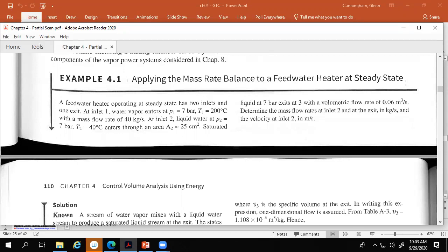So what they have is a big fry kettle, and it's a double wall, big stainless steel thing, and they flood it with steam, 400-pound steam, and that steam condenses. It transfers heat into the cooking oil that has all the Tostitos in there just cooking away, and that's how they maintain a constant temperature in that cooking oil, because if they supply that with the same pressure of saturated steam, that temperature is locked.